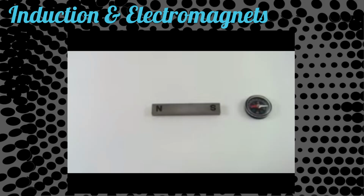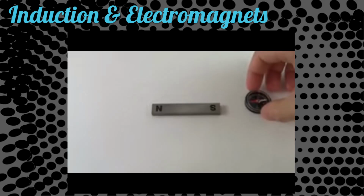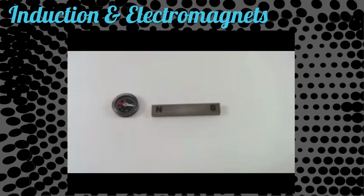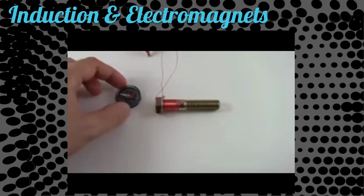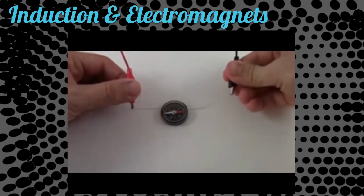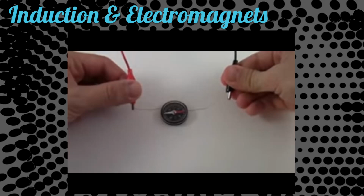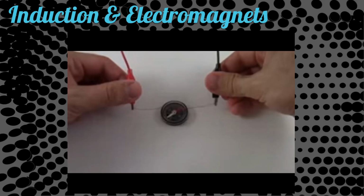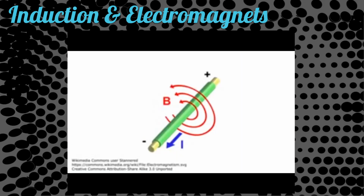You can also take a compass, which is itself a small magnet, and move it around near another magnet, and the needle will point in the direction of the magnetic field. So how does a coil of wire manage to behave the same way? It turns out that moving electrical charge, or current, creates a magnetic field. Watch what happens when I connect this piece of wire to a battery. It makes the compass needle move just like a magnet did, so we know the wire must be creating a magnetic field. This magnetic field takes a circular shape around the wire like this.